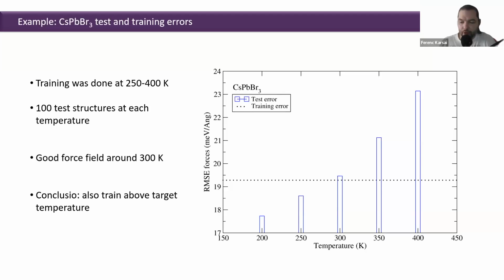Yes. If you want to make really sure, just run a quick on-the-fly relaxation up to some 10,000 steps, throw it away, and start from scratch with that new configuration. This you can also do. So basically, running all the kind of tests that you would run on a molecular dynamics simulation in order to check whether this is a good MD trajectory. Exactly. The molecular dynamics has to be correct, otherwise you're screwed.